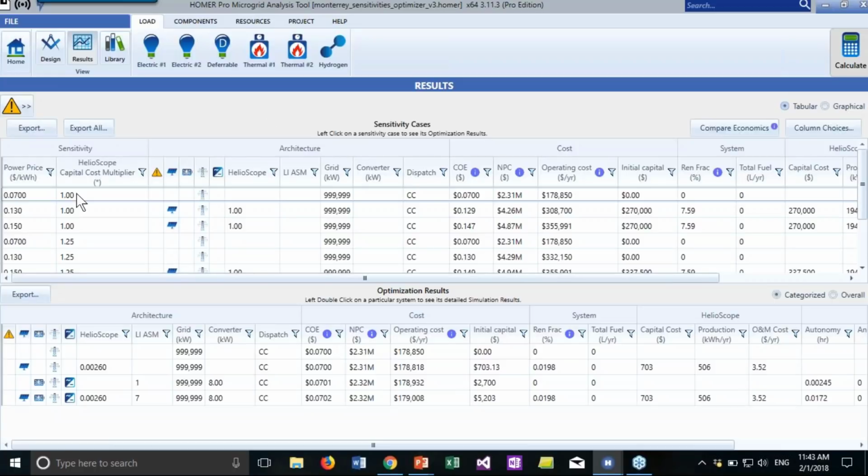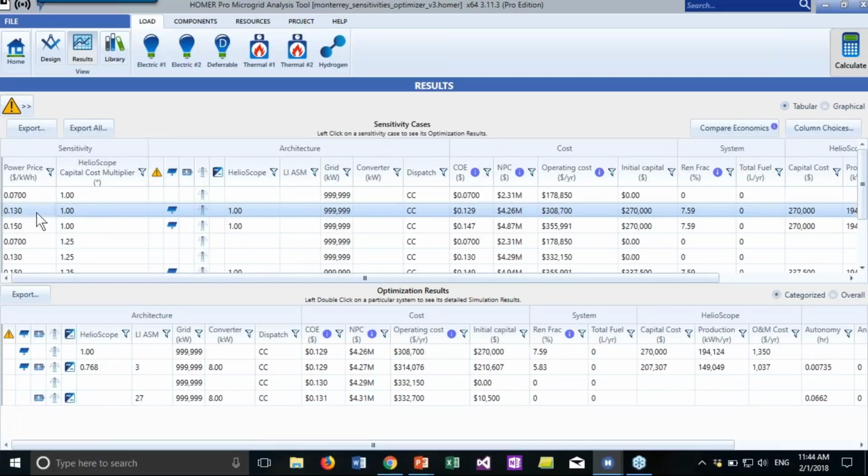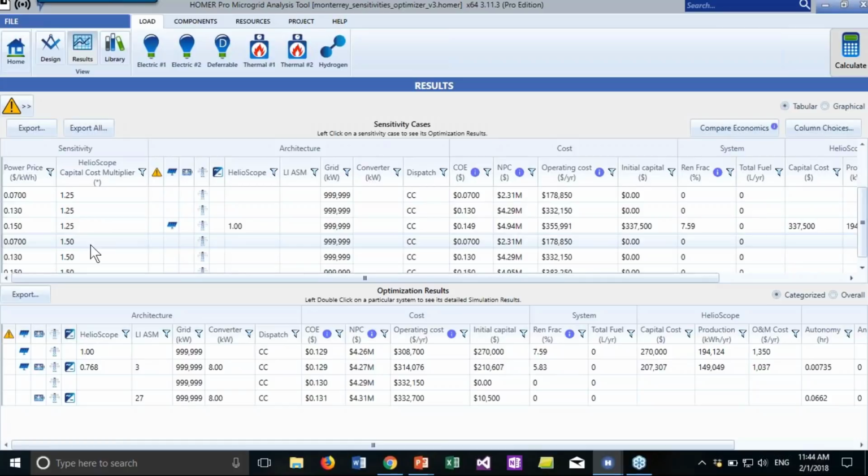And as you can see, we didn't talk about this yet, but given our case here, with the 13-cent power price and the $2 per watt PV installation price, here it's recommending that in this case with the PV system only, you should install all of the space that you had for your PV allotted. But if you're combining it with storage, maybe you'd want to consider a smaller PV. And that's actually a surprising result. So let's see if that's common across the board.